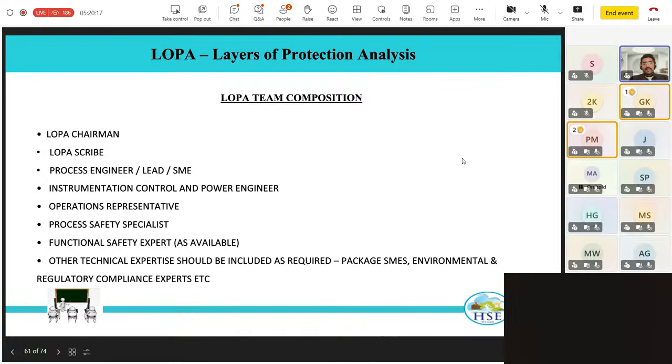Their argument is that many a times the operator may have left that bypass valve open, which would be an unrealized error, because by no means would they know that. So they insist that the cumulative flow through the main control valve and the bypass valve should be considered for PSV sizing, which many argue is an over-conservative design and an overkill. But that is how BP has been doing it, and I really appreciate their conservative approach.